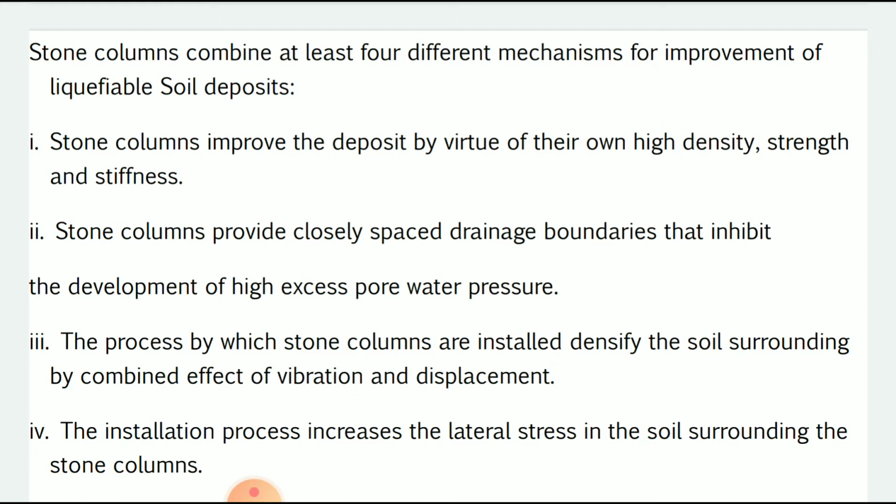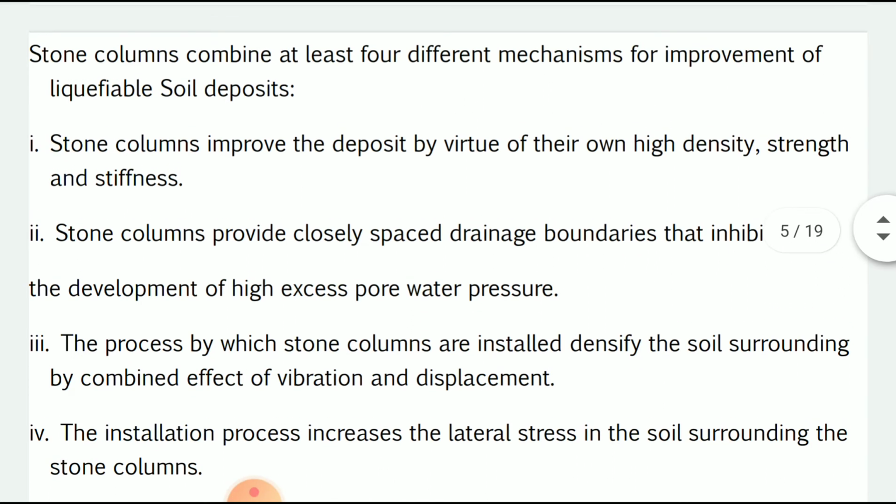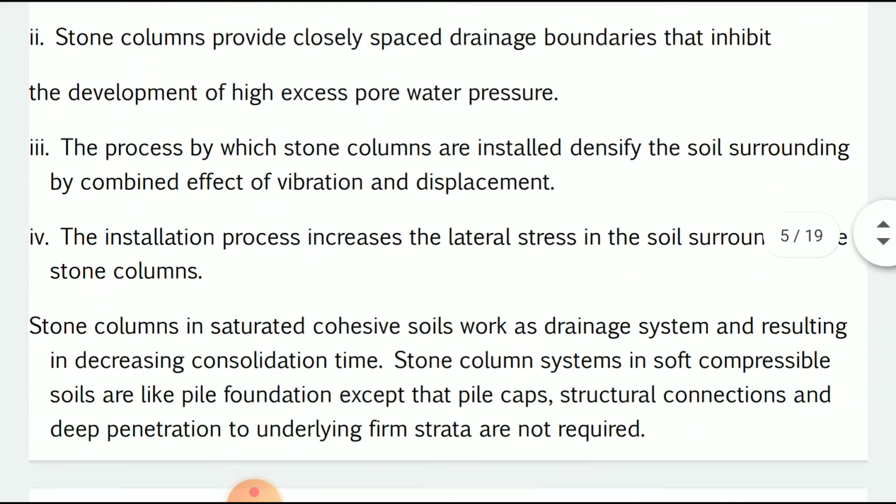Then the process by which stone columns are installed densifies the surrounding soil by the combined effect of vibration and displacement. The installation process also increases the lateral stress in the soil surrounding the stone column. So this is all about the stone columns.